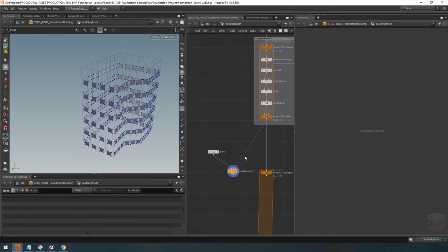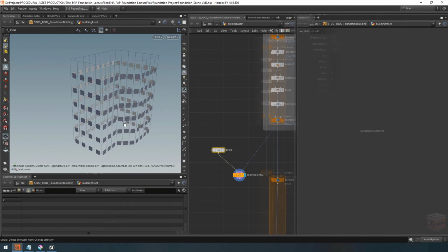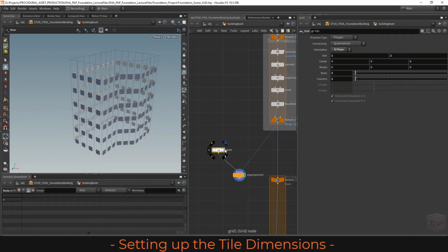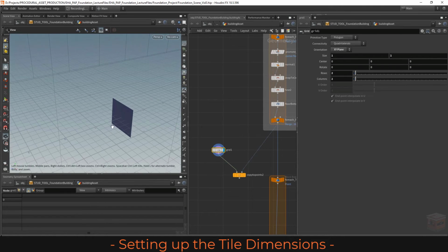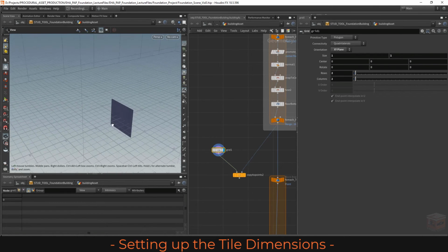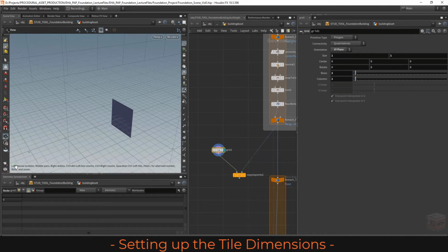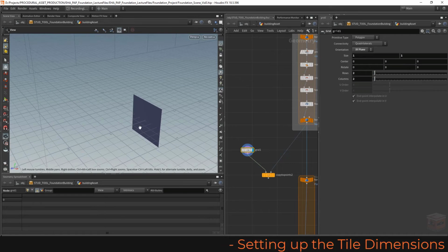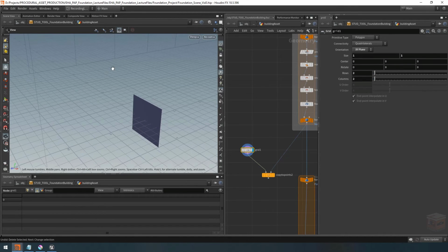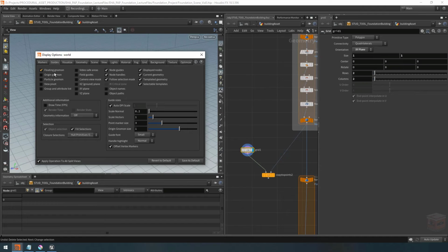And yeah, let's have a closer look at our grid itself. So right now, these grids are basically orienting towards the positive Z direction in the world. So if I look up close to my grid here, where it is located, I can of course use the grid itself, but this won't tell me the direction that I'm looking in. And here in the corner, you can see this little gnomon in the corner for the directions, but it's overlapping. So you can also pull up another one that's native to the world center. We can do that with the D button. Then we go to guides, and in here we can find the origin gnomon as well.